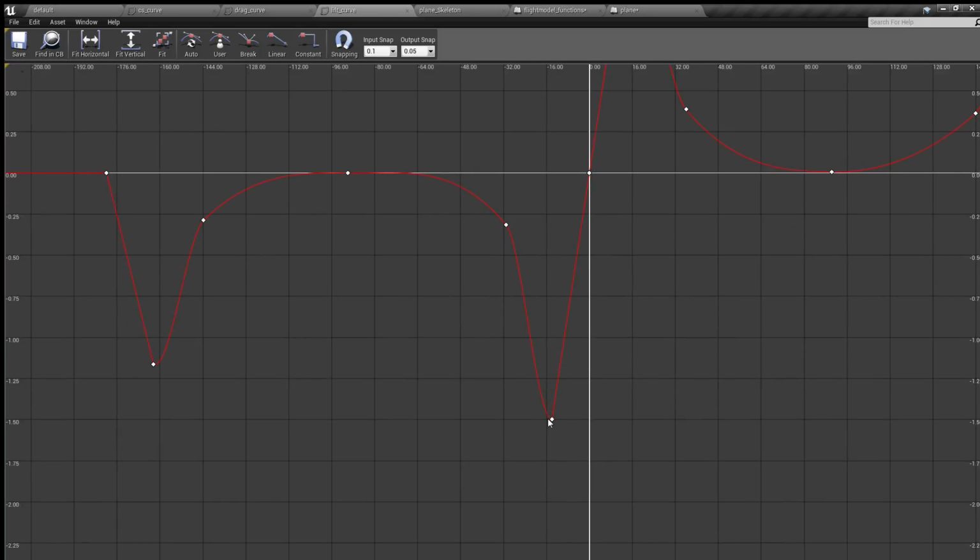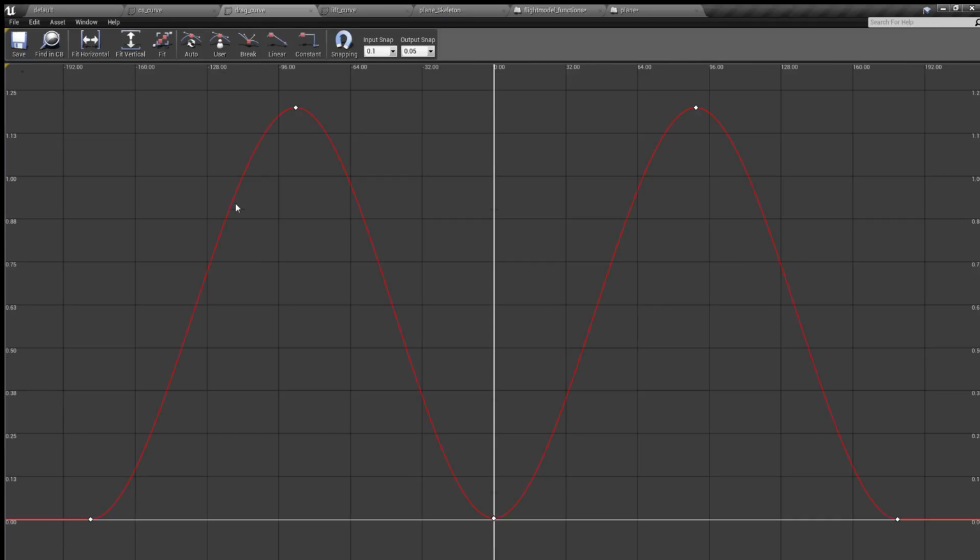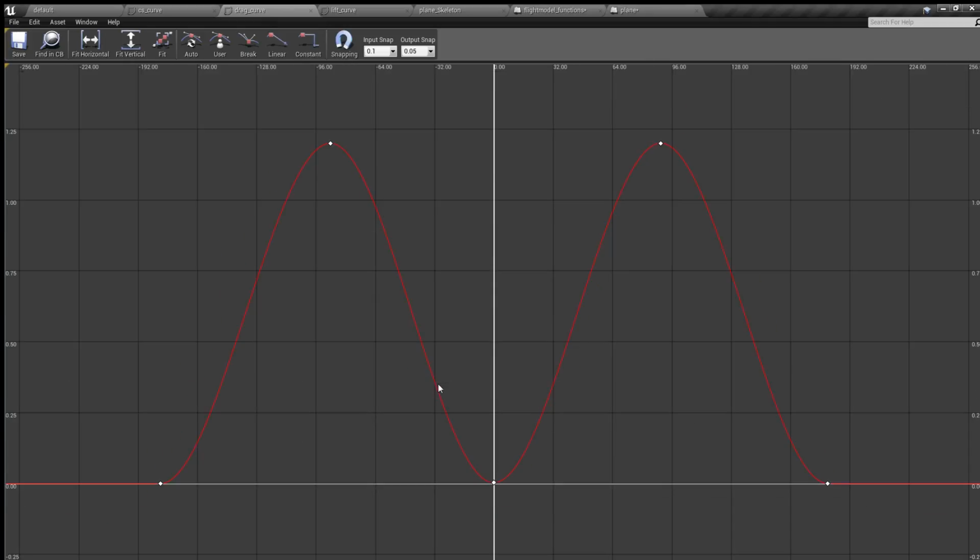There's also another part of the curve. If the angle of attack is negative, in other words, if you push down hard, the wing will actually generate negative lift. Again, diminished lift if flying backwards. Next we have drag, or actually just one component of the drag. This is form drag, which varies with the angle of attack.